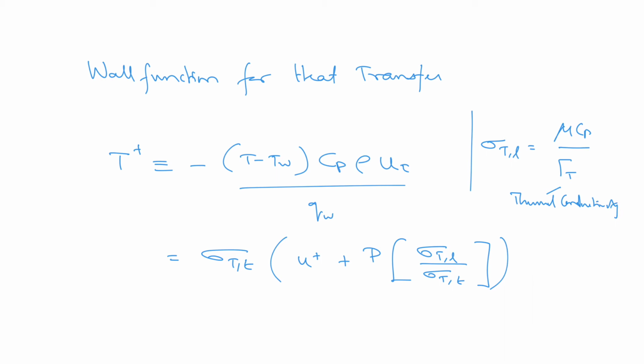This mu is dynamic viscosity. So this is the wall function for heat transfer problems, and you can use this for non-isothermal flows wherein you have heated surfaces, that is walls. So we have covered wall function for isothermal flows and non-isothermal flows, and we should note that at lower Reynolds numbers, log law is not valid.